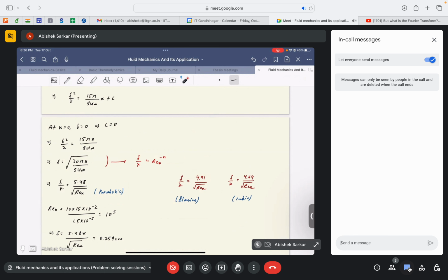So as engineers or mathematicians, accuracy of solution is quite important for us, right? Even though we are calculating approximate solutions, accuracy of the solution is quite important for us. Until now we assume that the Blasius solution is the most accurate one, right? So we see that even after applying cubic or parabolic profiles, we can still approach the same solution, but as the degree of the polynomial increases, the accuracy also increases.